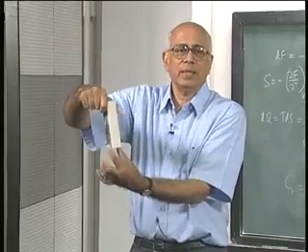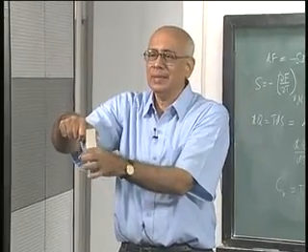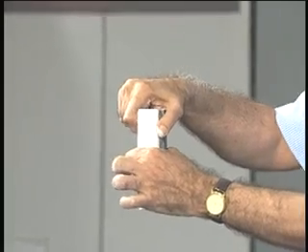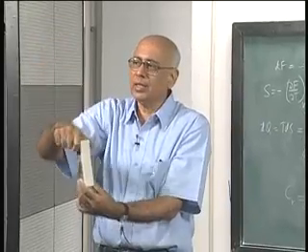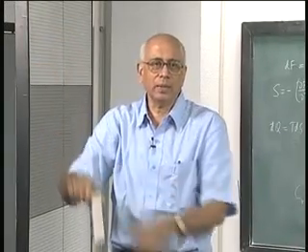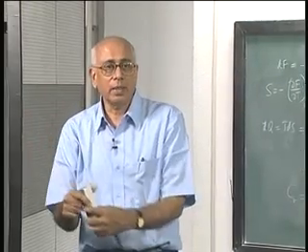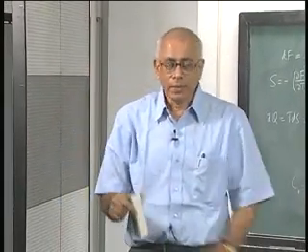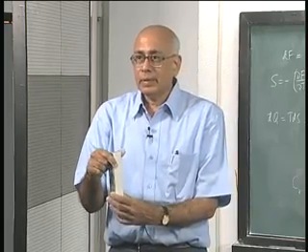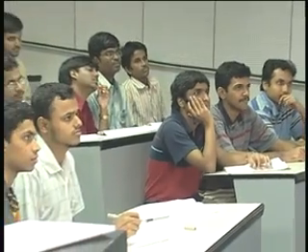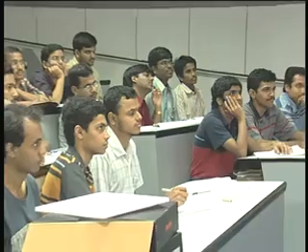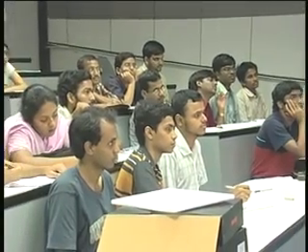If I take a piece of material like this and I pull it in this direction, then it could contract in the transverse directions, right. Overall there would be extension in this direction, and possibly contraction in the other direction, and the ratio of that contraction strain to the extension strain is called Poisson's ratio. On the other hand, if the Poisson ratio is negative, it means that if I pull in this direction it also expands in this direction as well.